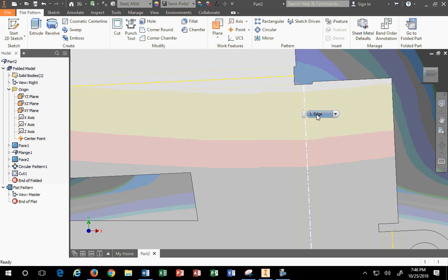And that you can actually then scribe into material. You can print it out 1:1. You can use an etching tool to scribe, especially if it's very precise. You can do that kind of stuff, and you can laser etch where you want things to be bent. There's a lot of things you can do. You can laser cut the whole thing out.